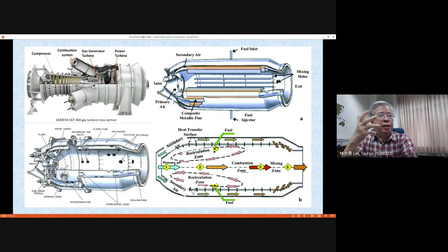But the most important thing I want to mention for the stationary gas turbine is that since they burn gas fuel or light fuel oil, you need some arrangement for the prevention of thermal NOx, because for the gas turbine combustor, you need good mixing, and therefore the spray atomization always has an optimal situation to produce so many tiny droplets.